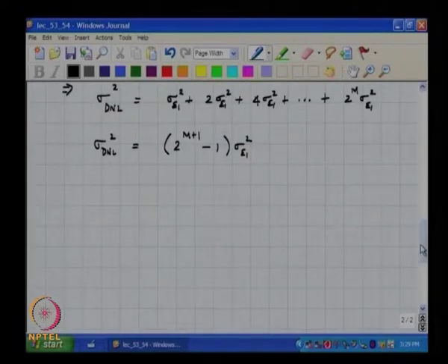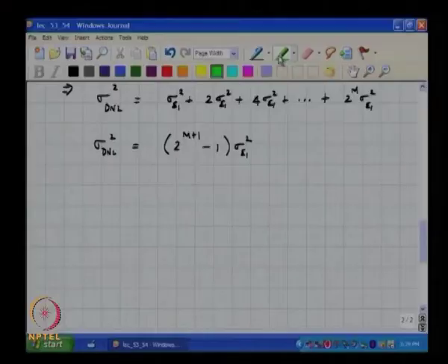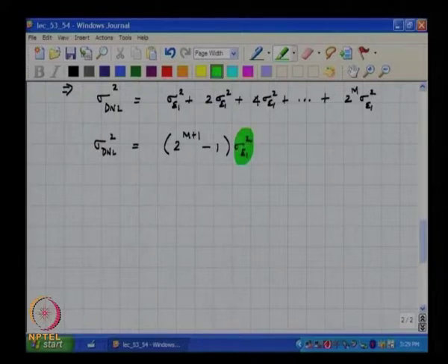Now, to achieve a certain DNL, please note that as designers, we are interested in finding what levels of matching one must have in the unit element, in this case that single conductance G. In other words, we are interested in what we should make sigma E1 in order to achieve a desired sigma DNL, right. That is the design problem.